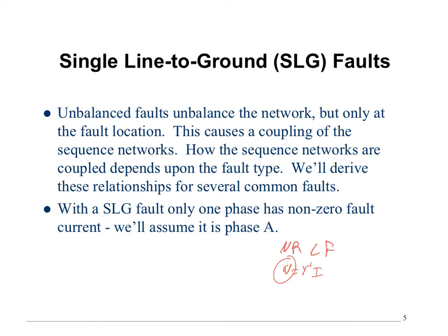The other option that you can do is flat start. Set your voltage to 1.03 per unit or 1.04 per unit, which should be the worst case fault currents, and then go ahead and calculate from there. All the bus voltages are at 1.03, 1.04. There's no calculations that are done. Okay, so that's another way to do it. Those are the three options: 1, 2, 3. This is the best, but it's rarely done because most people in this room don't even know how to spell PSSE.